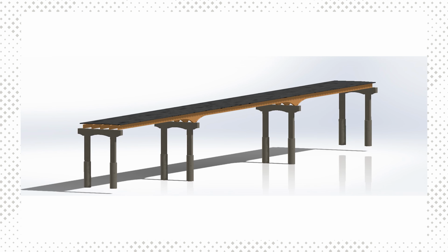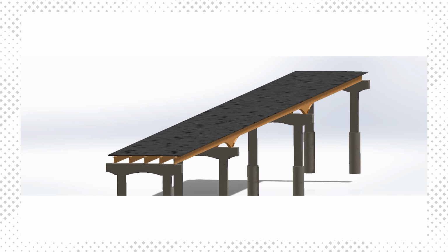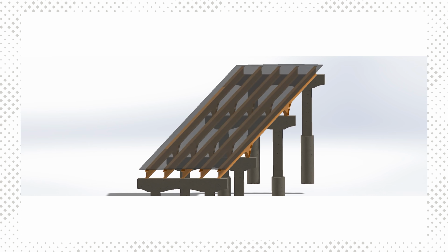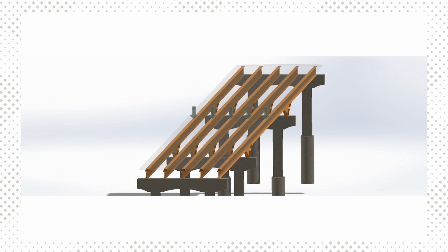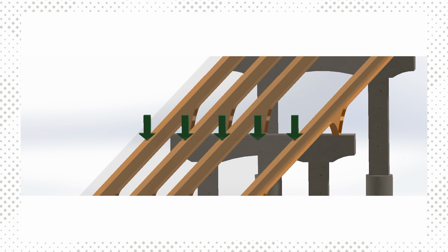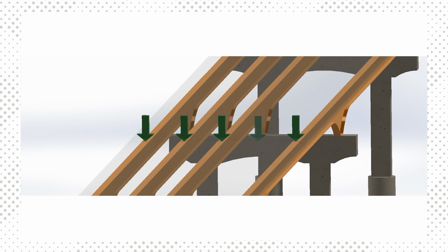Load path redundancy is achieved when an alternate and sufficient load path exists. Typically designed and detailed structures allow for a level of load path redundancy that enables the structural system to carry loads after damage to or the failure of one or more of its members. These details include the use of multiple girder lines and continuous decks connecting the girders.